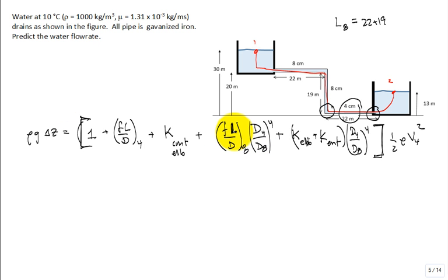So this length is a little bit longer. This contraction elbow, again, what we would do is I would put it as 0.3 for the elbow and a contraction of 0.4. There's not a lot of detail. They do have these, what do they call them? Anybody ex-plumber? Street elbows, where they come in one diameter, turn 90 degrees, and go out a different diameter. They're very expensive fittings.